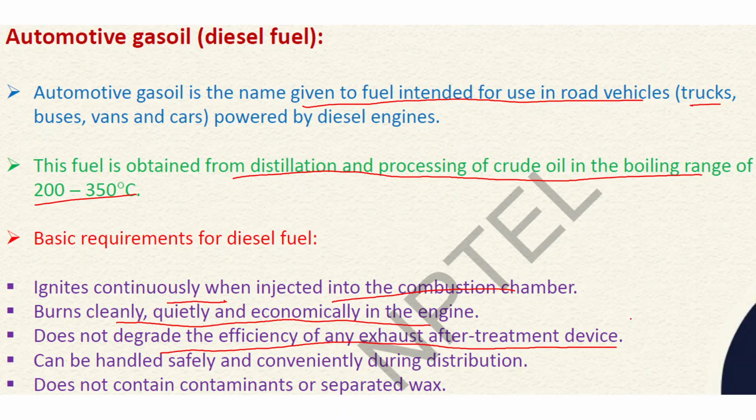exhaust after treatment device. Similarly as told in the gasoline section, after the combustion, the flue gases are ejected from the engine, and for that purpose, some exhaust after treatment is done, so that the harmful gases do not emit directly into the air. For that, some after treatment devices are available in the engine. So, if some impurities are present in the diesel fuel, that may deactivate the catalyst used in the after treatment devices. So, they should not be present in the diesel fuel.